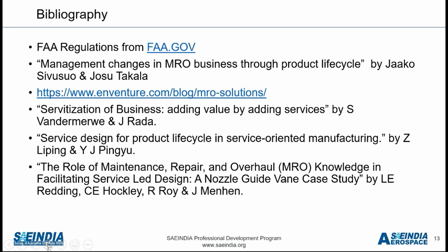But based on the way the aircraft industry or aerospace industry has evolved, accordingly they have come up with this scheduled maintenance checks frequency. So the A check is a very early check, where we are talking about 200 to 300 flight hours. Then we talk about the B check. The B check is somewhere around within one year, so 12 months. And again, these checks vary in terms of criticality.